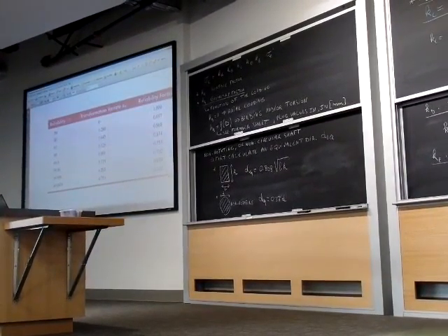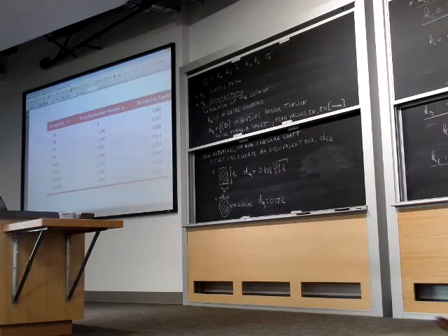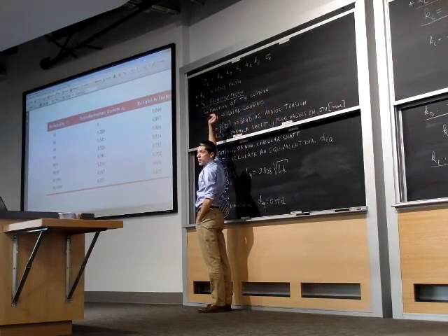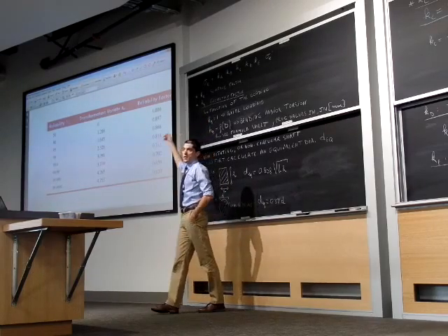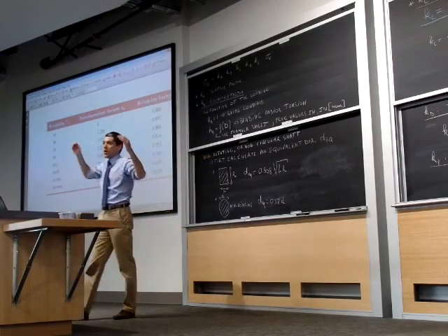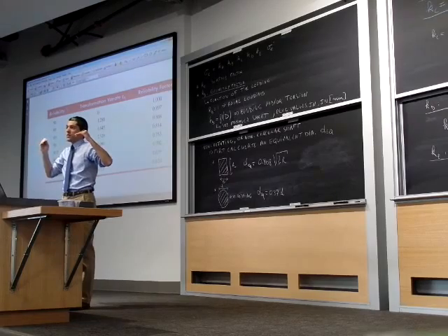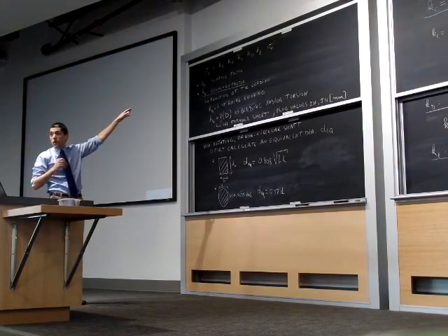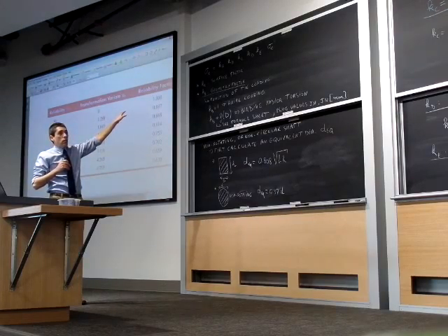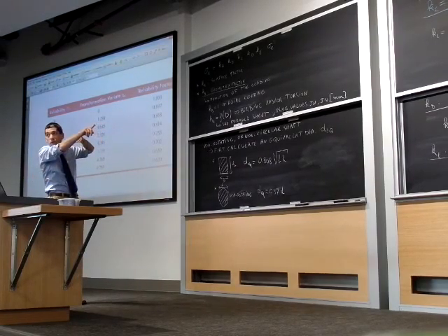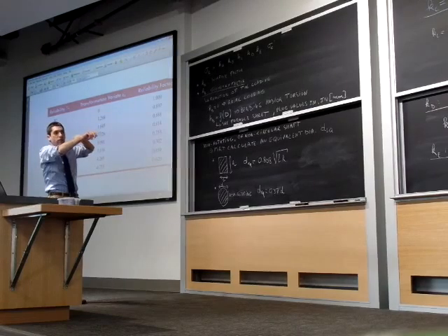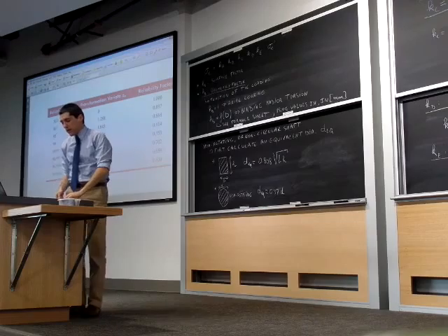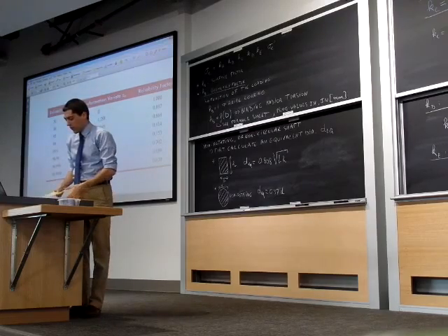If you decrease your reliability factor, then you will decrease sigma E compared to sigma E prime. And so that is going to result in a thicker mechanical element because you're underestimating your sigma E, right? Because you're multiplying sigma E prime with a factor that is smaller than 1. So your sigma E will be underestimated by a higher reliability, the need for a higher reliability, and that will result in a higher or a thicker mechanical element.